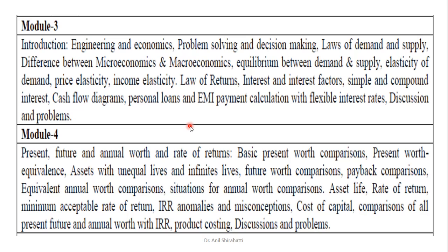Suppose strength is important, so instead of aluminium, you can make the shaft with either mild steel or stainless steel. But if you look at it from the price point of view, the difference between the mild steel and stainless steel is almost 8 times. It will become costlier if you are doing the shaft with stainless steel. So there again cost will come into the picture.